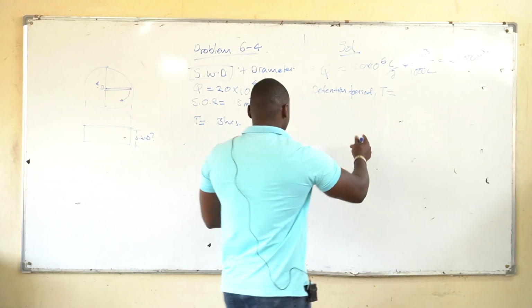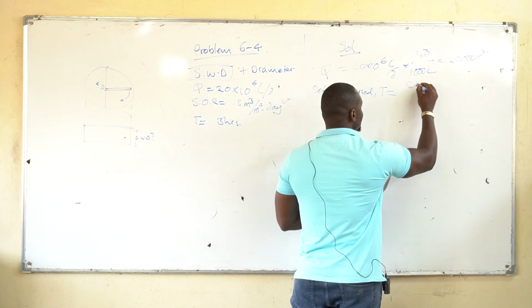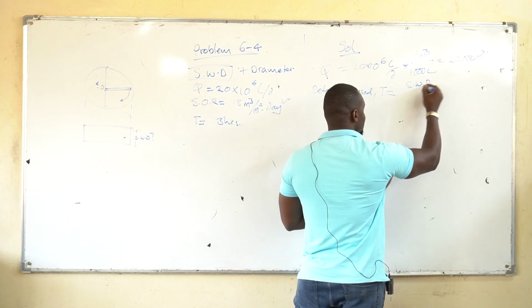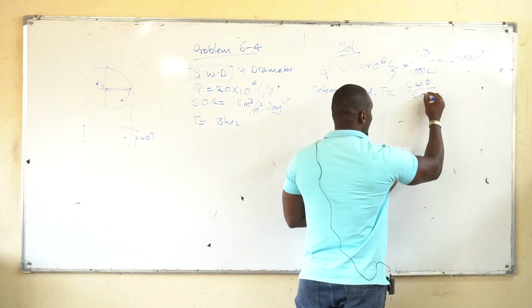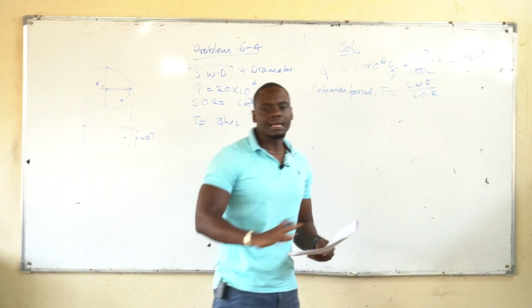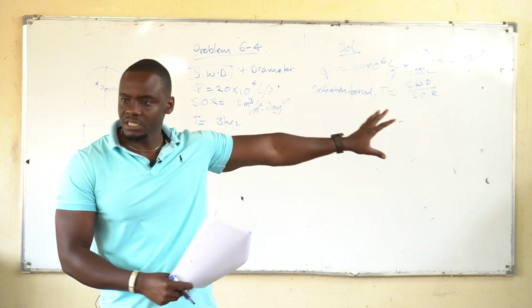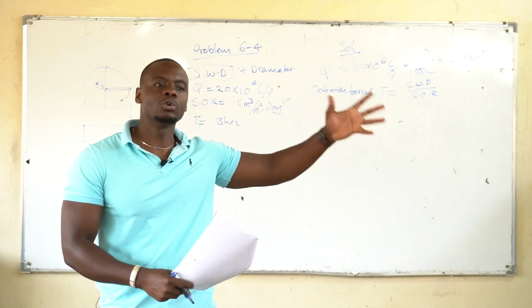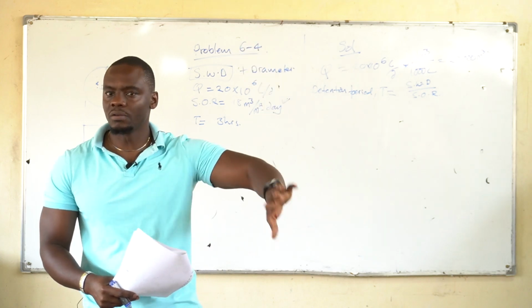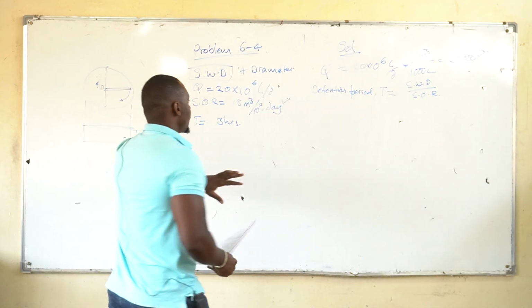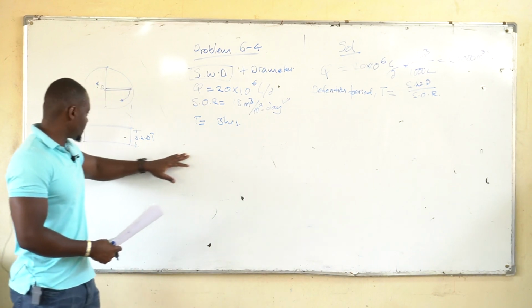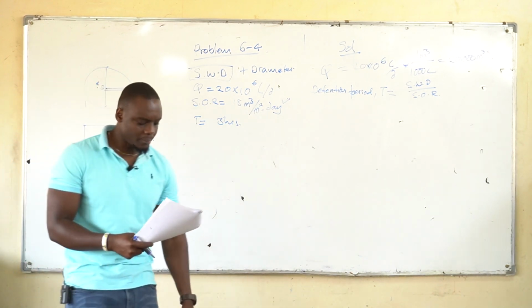Okay, so time in this case should be distance, which is the SWD, side water depth, divided by SOR. And it's nothing that you even need to memorize, because this is just a basic equation that we've always known. Time will always be equal to distance over speed or velocity. Okay.